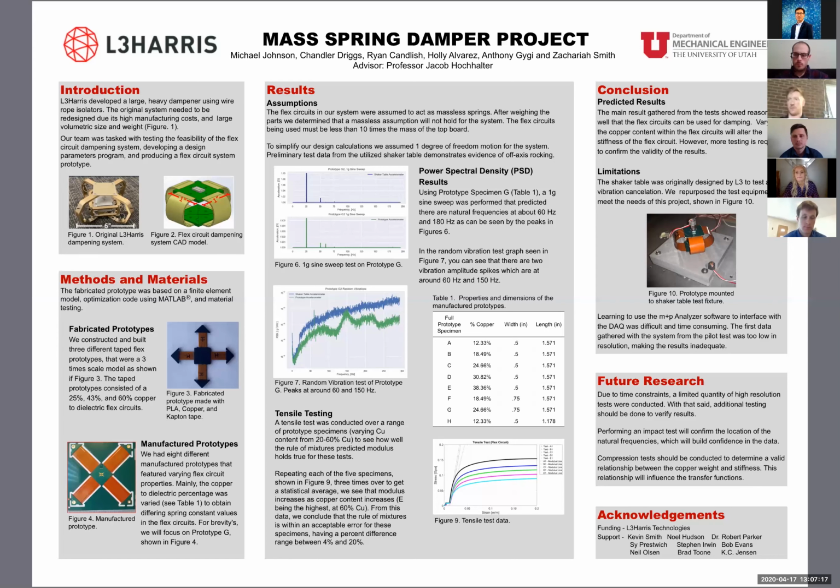Like Holly and Ryan said, I'm just going to talk a little bit more about the tensile testing and why we did it. Tensile testing is a way for us to validate how we were going to fine tune the natural frequency for our prototypes.